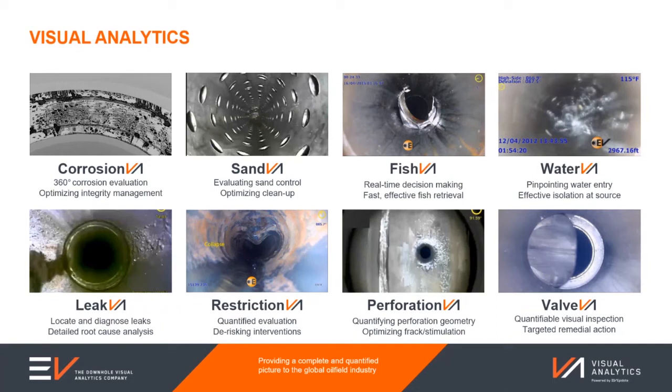Yeah, and I think our second case study was also very useful in showing that it's not only exactly where it's coming from, but also the surrounding areas. I've seen a number of times where we've gone in to find, let's say, a leak or an unwanted inflow, and the primary solution is, well, let's just set a straddle. And then you realize that the surrounding area is close to becoming Swiss cheese. There are so many sites of corrosion or erosion that you've got to actually straddle off quite a large interval in order for this to be effective.